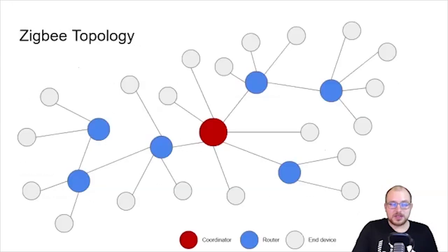So in terms of the Zigbee topology, Zigbee can form mesh networks, which is one of the greatest things about it, and it works mainly, most of the time rather. Given that there's only one coordinator in any Zigbee deployment, routers are used to extend the range of the network and deal with, say, thick walls in a home, or well-insulated metal-clad surfaces. So routers are generally your way of extending the range of your Zigbee network and dealing with problems as well.